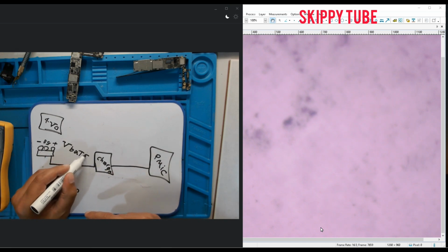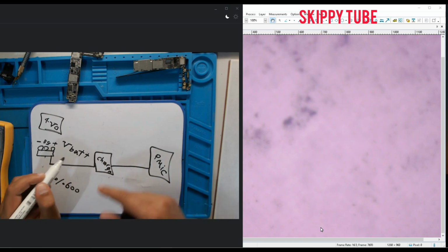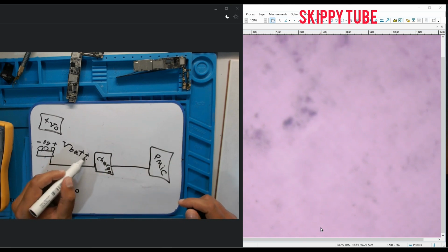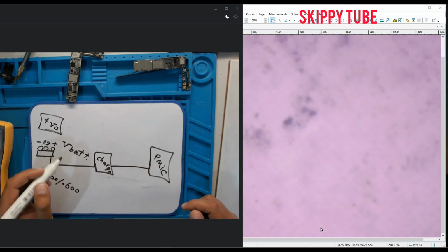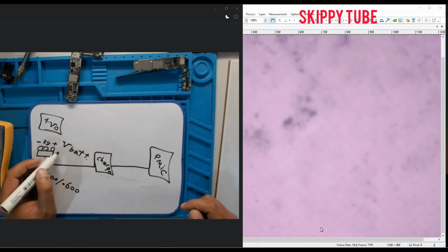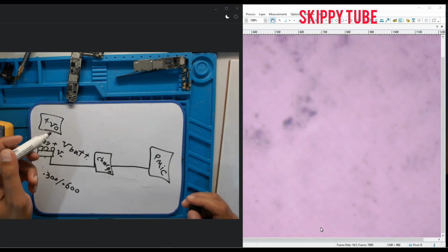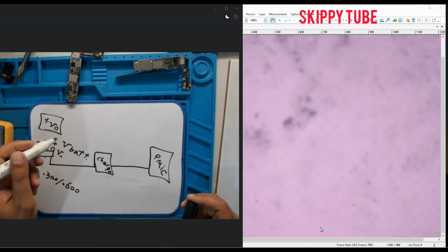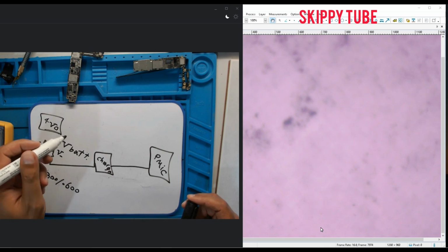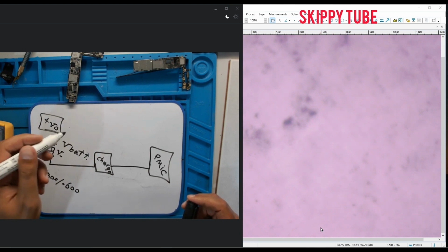Let's just make this small. This side is VBAT. This is the node, pay attention to this one. Sometimes it is written V battery, or on the iPhone schematic diagram sometimes its name is PP_VBAT, PP underscore VBAT.